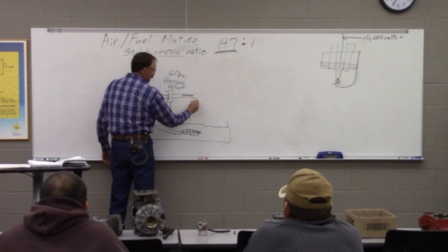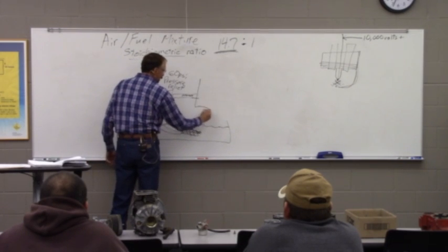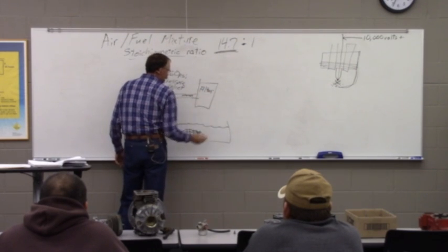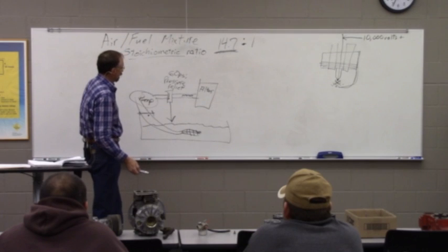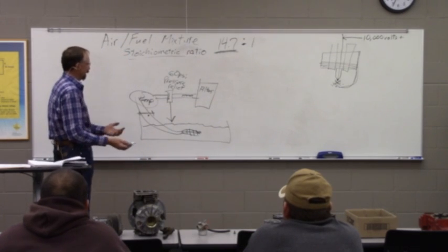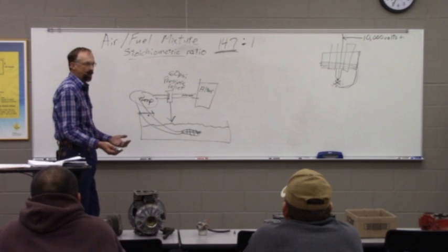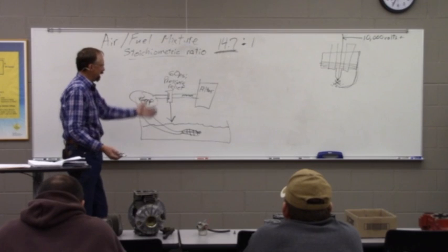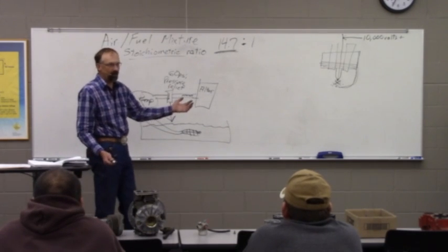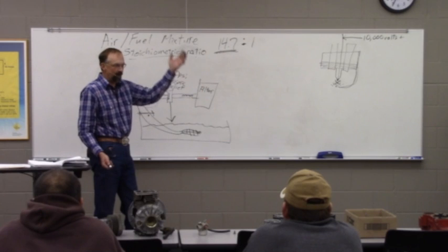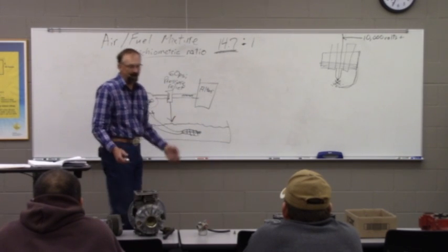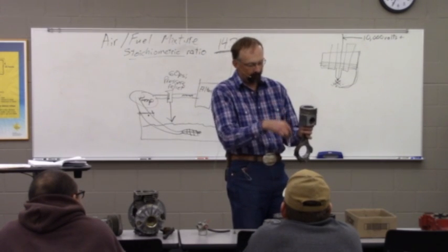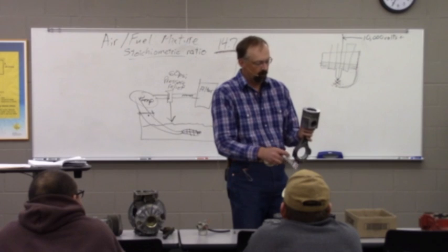The next thing in our lubrication is typically a filter. Most of you have seen oil filters, and the idea there is to catch any debris and trash that may have wound up in the oil. We had a lot of debris and trash back when we had carburetors. We had so much carbon that you'd have a lot of crumbles of carbon making it past these piston rings. Well, anything that makes it past these piston rings winds up in that oil pan.